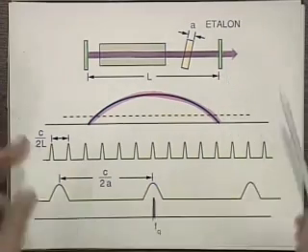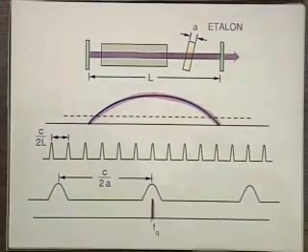This is, as I say, a very popular way of getting single frequency, and it's used quite a bit. It's a pain in the neck to put things inside the cavity, because any loss then will start cutting your effective gain down, and your laser output power will drop. But this is a convenient way of getting single frequency. So you don't have to worry about the fact that lasers can put out many frequencies. There are techniques to select only one and to be able to tune that.